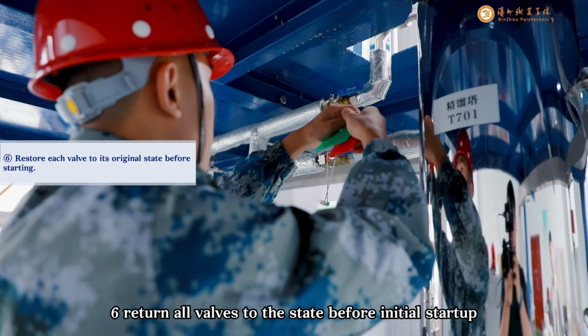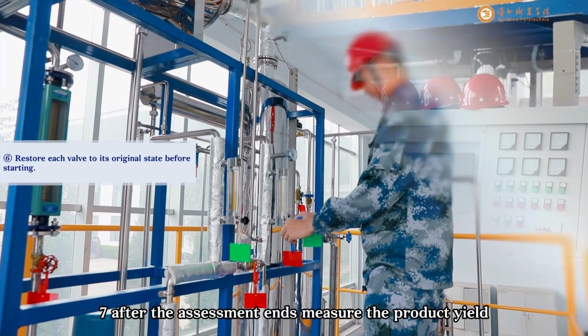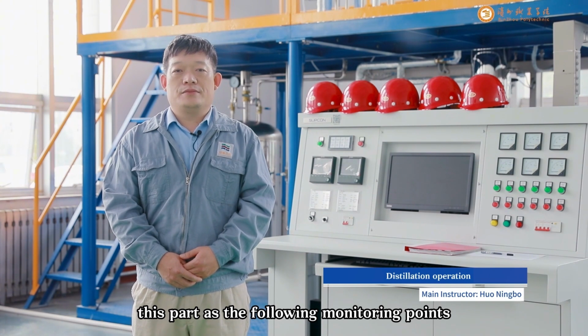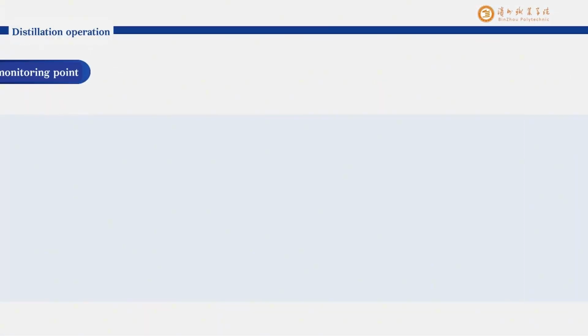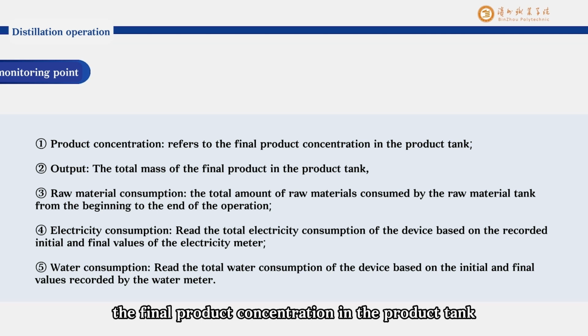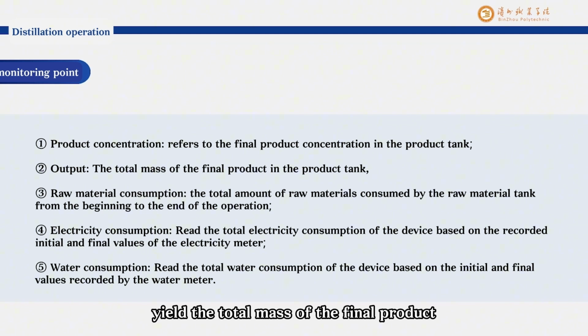6. Return all valves to the state before initial startup. 7. After the assessment ends, measure the product yield. This part has the following monitoring points. 1. Product concentration, the final product concentration in the product tank. 2. Yield, the total mass of the final product in the product tank.